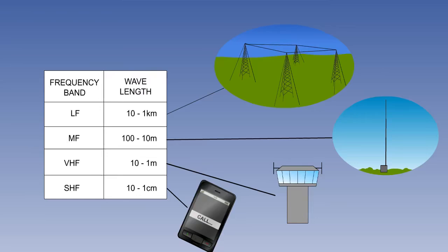The size is particularly important. Ideally, it should be half the size of the wavelength of the radio wave. However, a quarter of the wavelength is nearly as good and has the advantage of being smaller. As a result, medium wave, long wave, and very long wave transmitters have huge aerial complexes, whereas VHF and other short wavelength antenna can be very small, such as in your mobile phone.